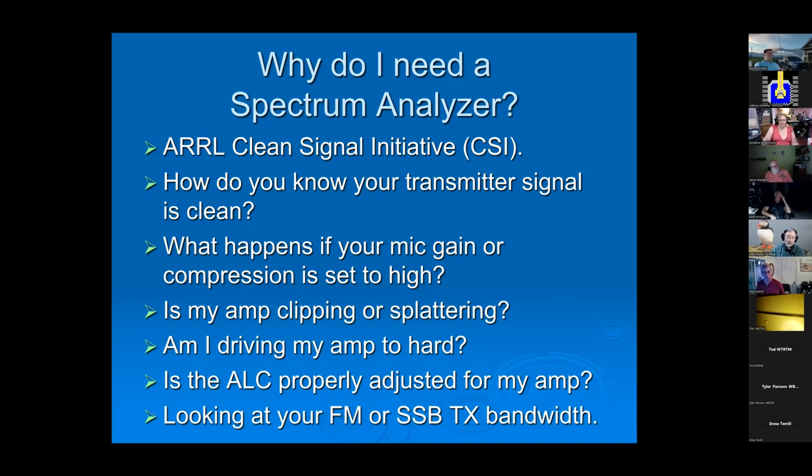I think everybody by now has heard me talk about IMD. Typically what gets stated in the specification is cherry-picked: the best band, the best frequencies, giving the best IMD. It doesn't tell the whole story.